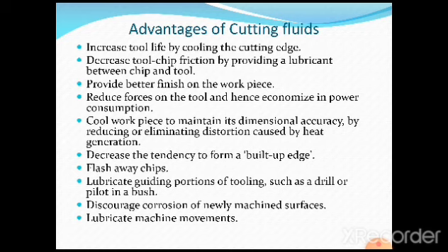The main intention, if we go on using the cutting tool with continuous resharpening, because how we have defined tool life is the time interval between sequential resharpenings. So in such a condition, it is necessary that the tool life be increased, because you are giving the cooling action with the help of the flow of a cutting fluid, thereby protecting the cutting edge of the cutting tool and making it work for a longer period of time during the machining process.